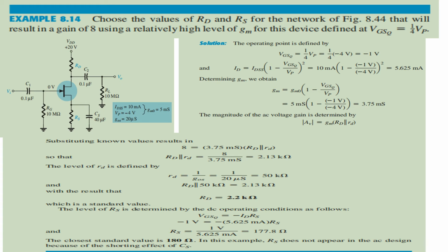So here I'll describe this circuit. Here it is having a resistance between a gate terminal and a ground terminal. Then it has a source resistance which has been bypassed by a capacitance Cs. So at higher frequency, capacitance Cs blocks this resistance Rs, or it short circuits.